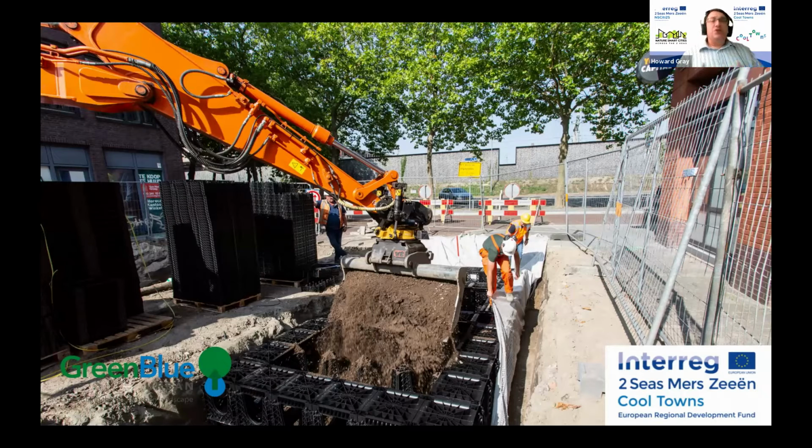Now, the storm water has the availability to go into this, so when it rains, it can flood into the tree pit. And actually, the soil mix means that up to 20% of that soil volume can be retained water, which the tree then can draw out of that when the weather conditions are right. There doesn't seem to be any limit to the amount of water that a tree can draw if there's water available and the climatic conditions are okay.